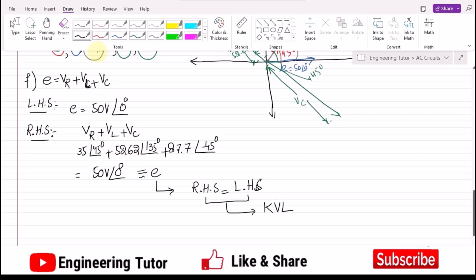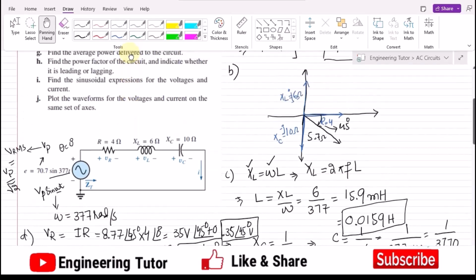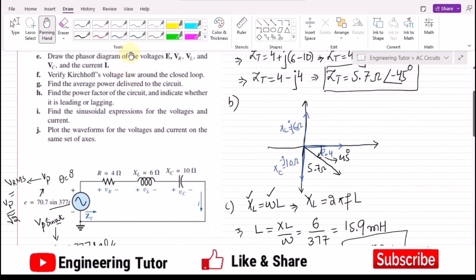Okay, so that is a proof of KVL, that the phasor sum of all the voltages in this loop is equal to the total voltage which we have here. So that is the solution of part F. In part G, we have to find the average power delivered to the circuit. By the same method which we have previously seen, we can write here I E and the angle between them, which is cos of theta.